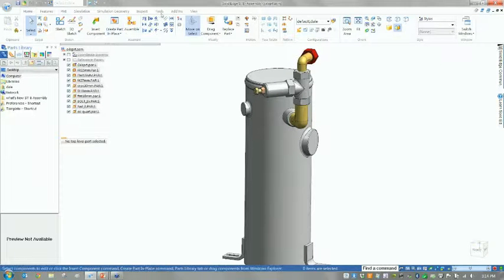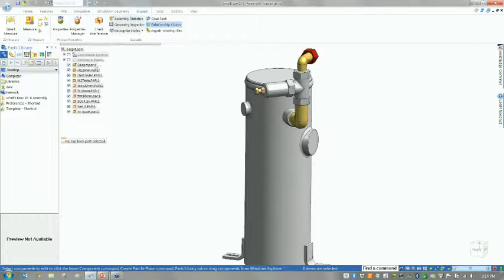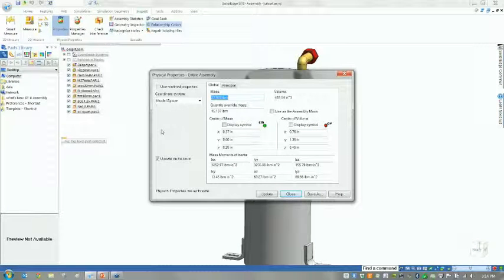And then as I come back to my mass properties, that's the whole theme of this one, it's going to give me 2 different weights. 37.9, roughly 38 pounds, is how much this assembly is going to weigh with 1 quart of oil in it. The 1 quart is the 1 quart that we put over here on the left-hand side. 45 and some odd pounds is how much it weighs now because I went to the occurrence properties and put 5 quarts in it, right? I overrode that.